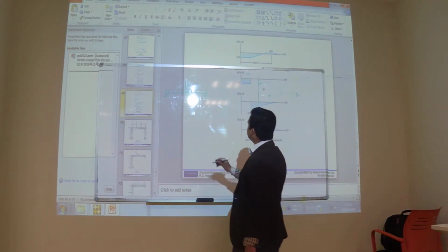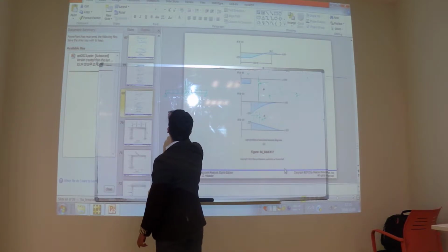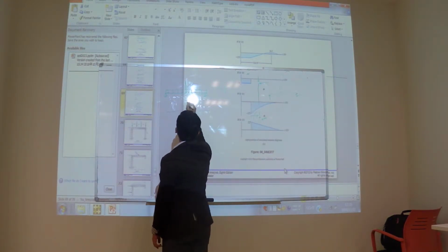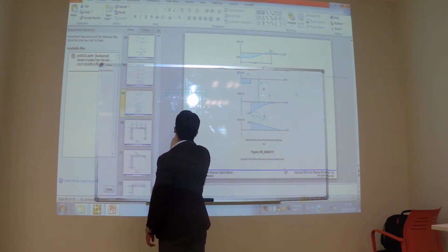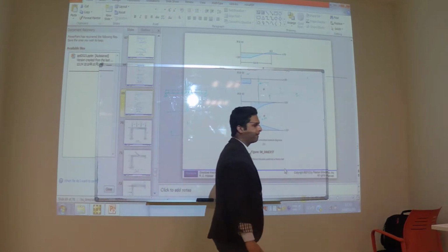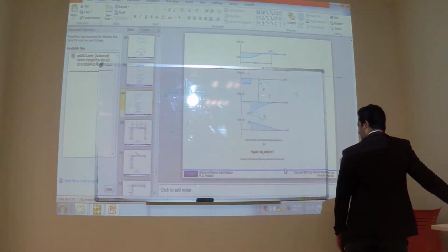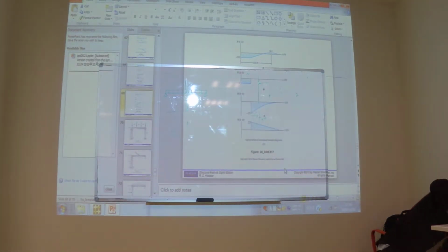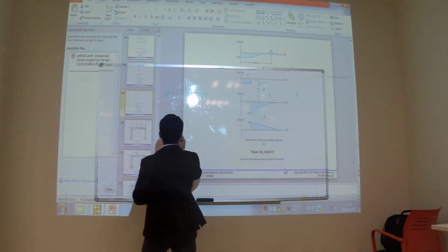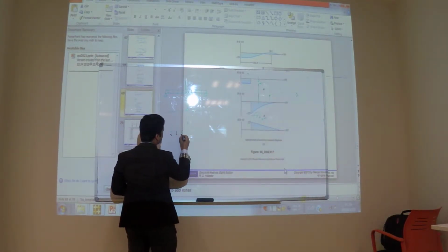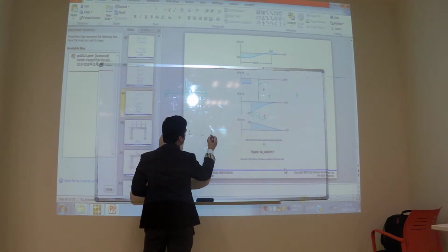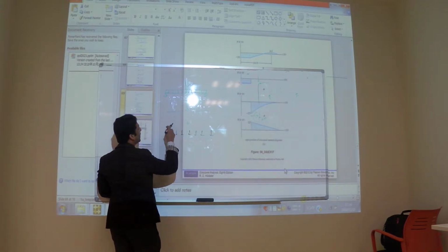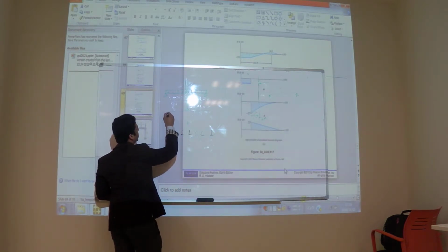You can divide this beam into two parts: one beam with the point load plus one beam with the UDL. Two states. And you will find the reactions.